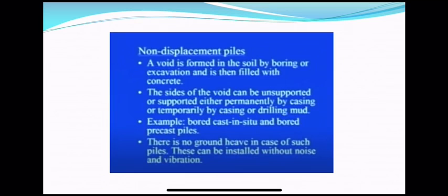It may happen that the walls of the borehole collapse. So how can we support them? Either permanently by casing, or temporarily by casing or drilling mud.